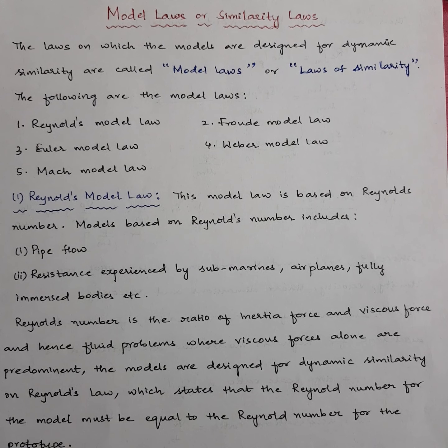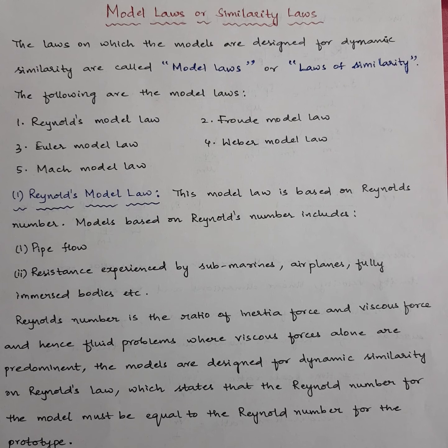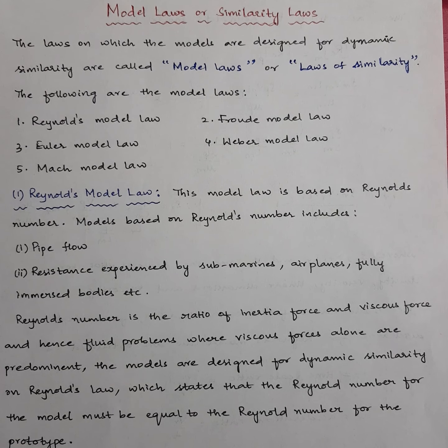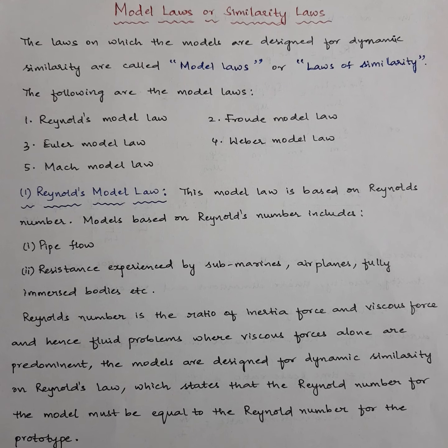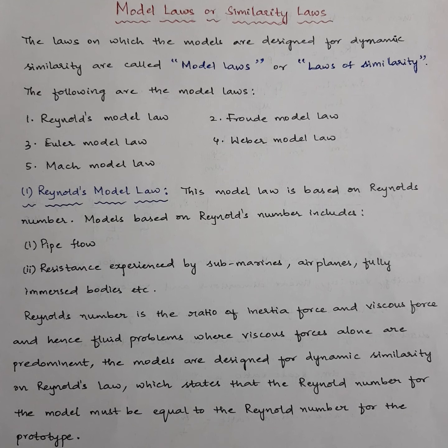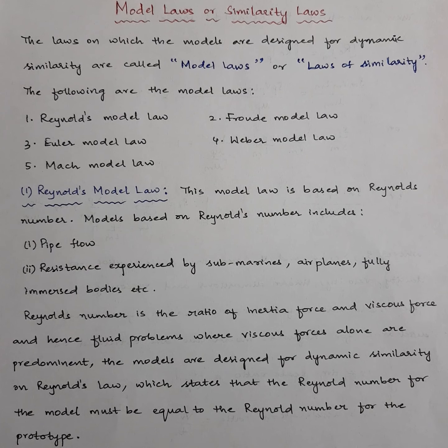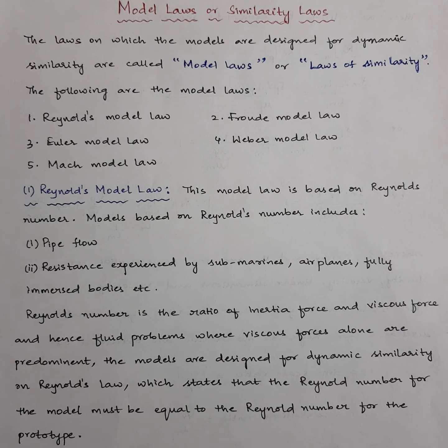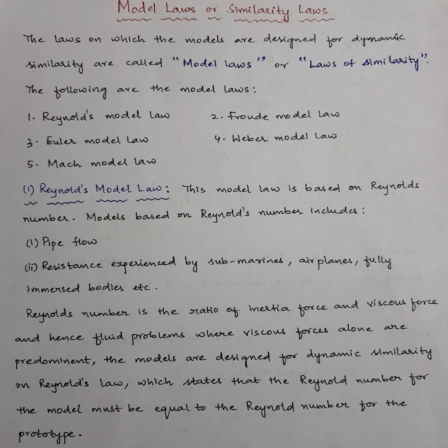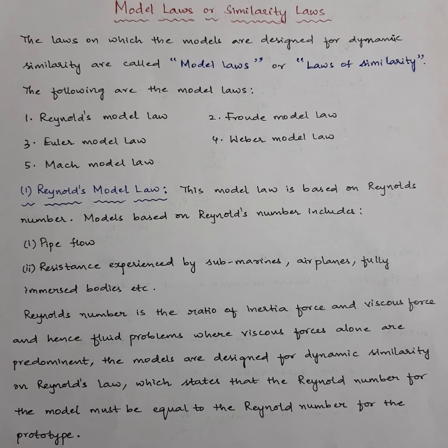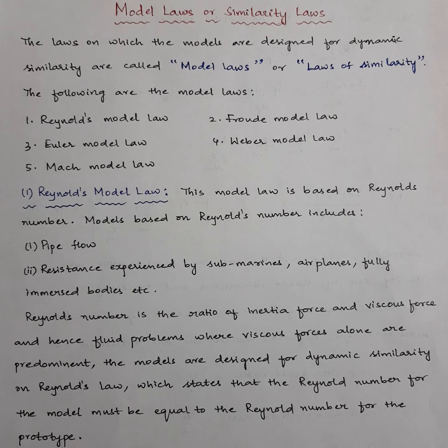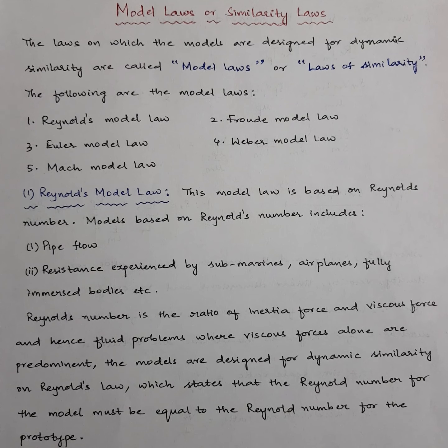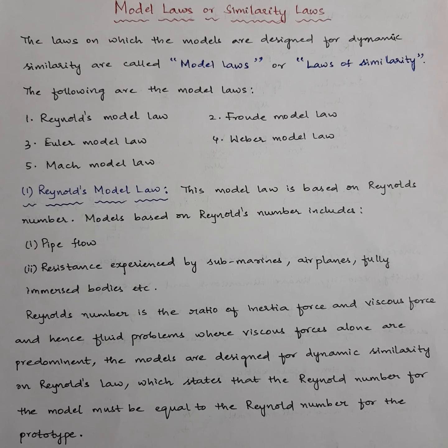What are model laws? Model laws are also called similarity laws or laws of similarity, by which models are designed based on dynamic similarity. You remember dynamic similarity? Dynamic similarity is nothing but the similarity of forces between the model and prototype. So these model laws define the similarity between the model and prototype in terms of forces, which means it's a dynamic similarity.